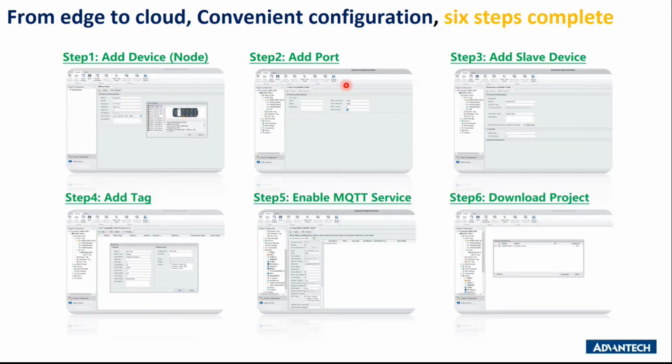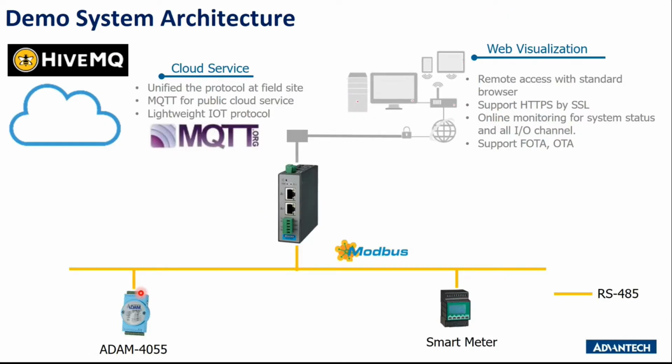The second one is for the communication. If you want to query the data, what kind of communication will you use, serial or TCP. So this is the communication part. Based on this architecture, this one will be our slave device, and this one is the master or client, the TCP client. This is just naming. RTU serial uses master and slave, TCP uses client and server. So this is just the term definition only.